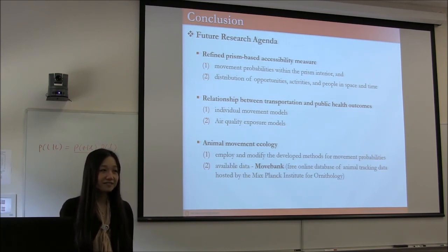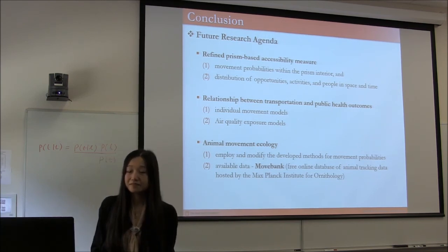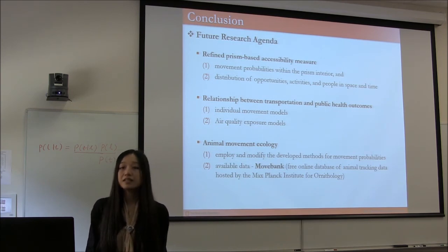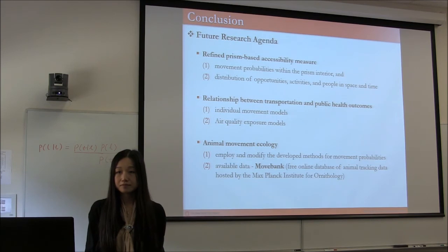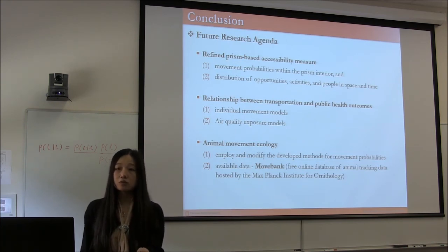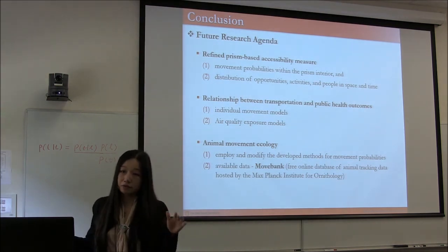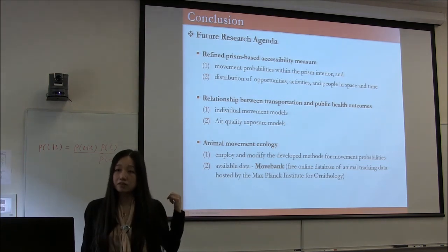Thank you. Any other comments? I just have one. The lambda parameter for the visit probabilities, that's Manhattan-based. Yes. So to apply this model to other cities, you would have to recollect GPS trajectories and calibrate your model. That's a very good question. One way is to use GPS data to calibrate that model. The other way is we do have traffic flow and travel time data collected by the DOT or some other transportation department. We can also use that to see what the average travel time between vertices is, and use that to calibrate the number.